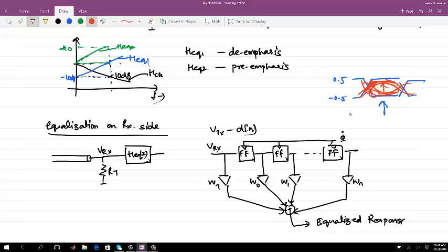Do you see from the picture that on the transmitter side I drew only 2 voltage levels, plus and minus, fixed signal swing. The flip-flops used for the transmitter side were digital flip-flops. You just pass a single sample. Whereas in case of receiver, you have a different voltage at different times.